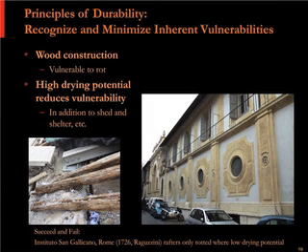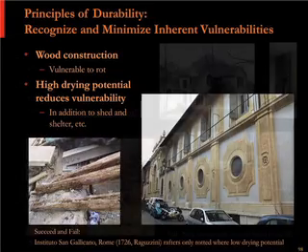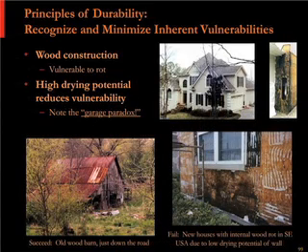So this is a 1726 building in the Trastevere section of Rome. It's kind of the equivalent of a hospital or a convalescing home. If you look at that roof overhang at the right, the rafters out there were really doing fine. Inside the attic, where they had a lot of venting and air circulation, the rafters were doing fine, despite the leaky roof in both cases, a really old leaky clay tile roof.